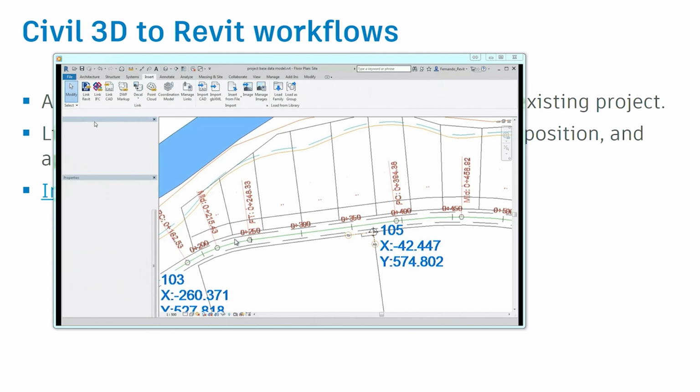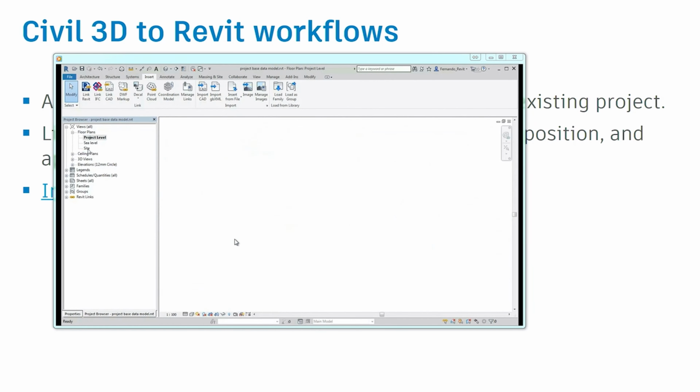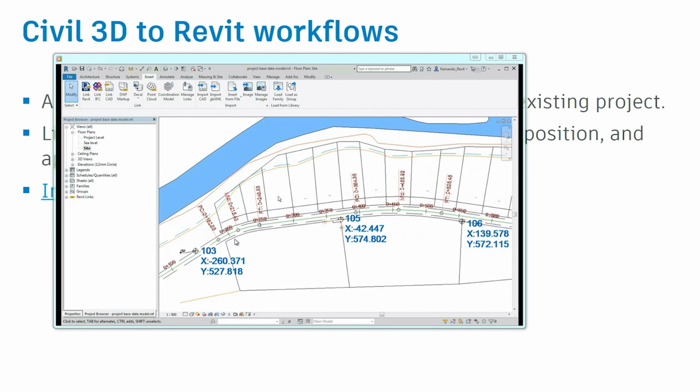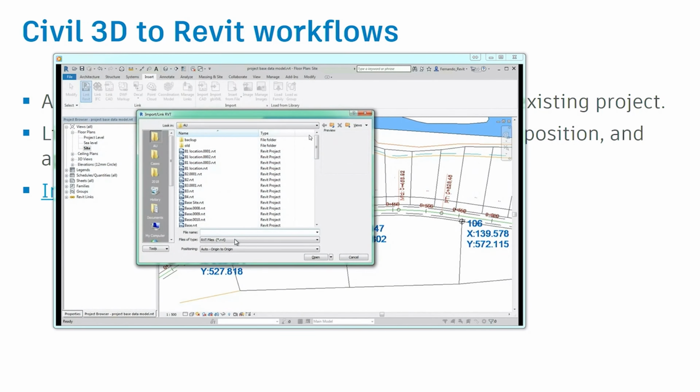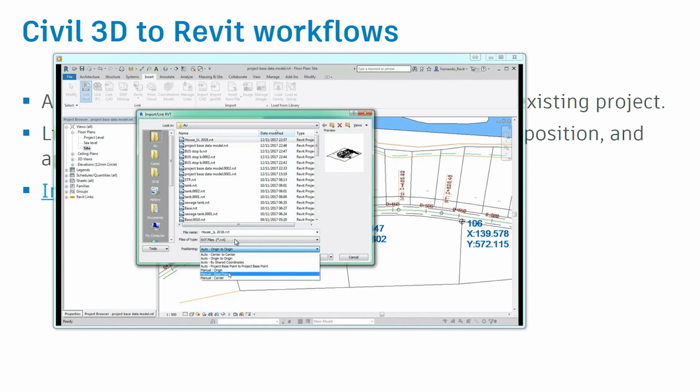We should work by default with the new ones, because if not, later when we insert to InfraWorks, you're going to land on the old coordinate system. If we have objects with multiple site properties, we need to be careful on that. I had a slide showing that part. So this is okay. I'm going to manually drag it, put it there, and then do some adjustments.